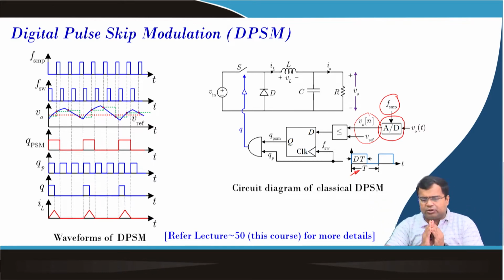So, the selection of duty ratio is important, but in a digital circuit you may update the duty ratio based on your switching frequency consideration. Because if you find that your number of skip cycles are reduced and more charge cycles are going, then you should understand that it is time to increase the duty ratio. So, duty ratio adaptation may be possible.